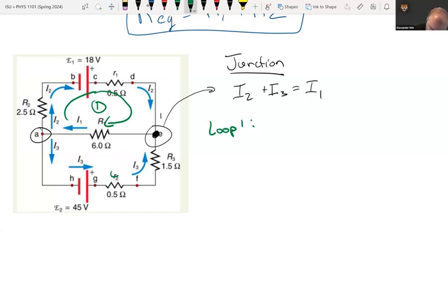Now, this is another place I want to indicate to be careful. A lot of people look at this and they're not sure, okay, is that a voltage gain or a drop across that resistor? Well, check this out. Whichever side the current is flowing into, put a plus and then a minus on all your resistors. So I'm just going to do that here. So we have a plus and a minus there. And again, I3 is connecting, so a plus and a minus there.